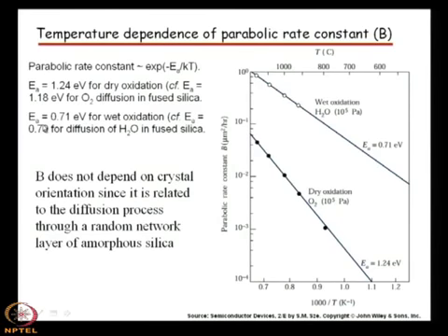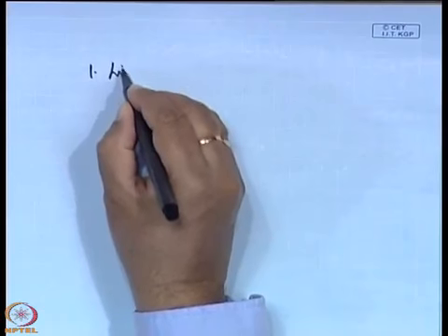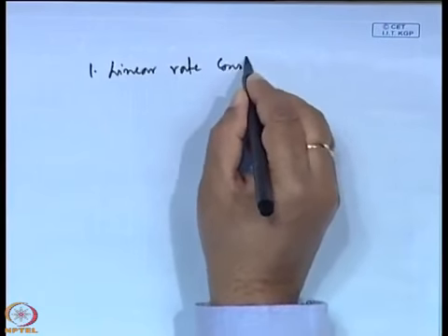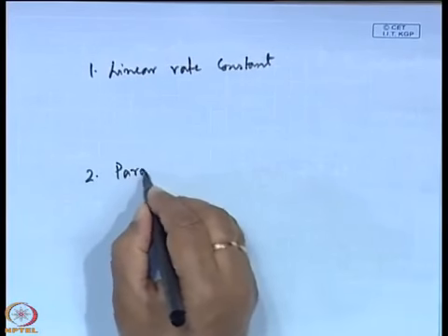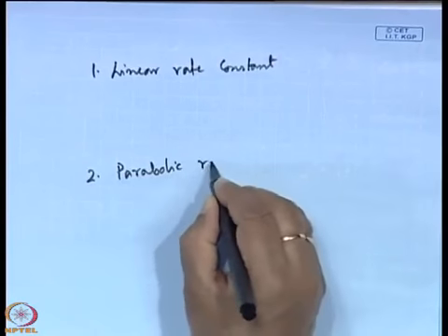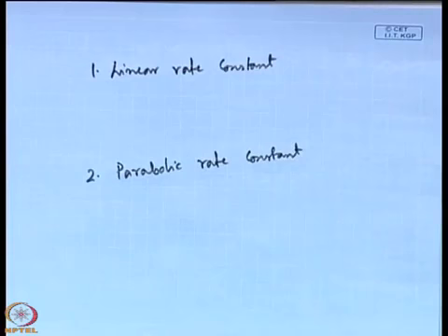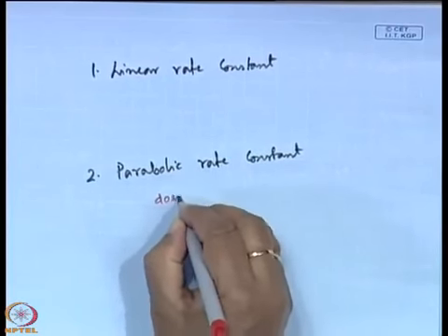So, we can summarize these findings: the activation energy dependence, number one is the linear rate constant, and number two is the parabolic rate constant. This parabolic rate constant does not depend on orientation.